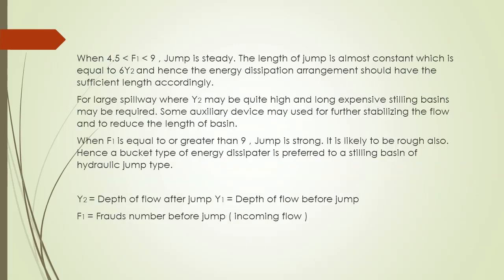When jump is steady, the length of jump is almost constant and hence, the energy dissipation arrangement should have sufficient length accordingly. For large spillway, long expensive stilling basins may be required, and some auxiliary device may be used for further stabilizing the flow and to reduce the length of basin. When jump is strong, it is likely to be rough also. Hence a bucket type of energy dissipator is preferred to a stilling basin of hydraulic jump type.